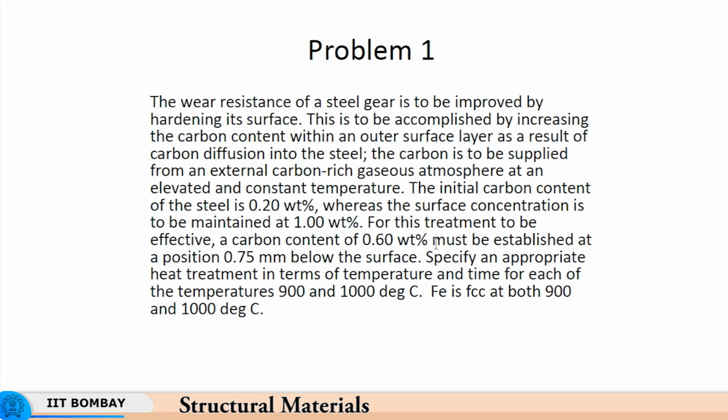So there is a gradient of carbon percentage from the surface to the interior. It is not a step change from 1% to 0.2% at an interface, otherwise that also would be disastrous. So there is a continuous gradient. A certain thickness will have 1% carbon, and as you go inwards, the carbon percentage will continue to reduce, and it will reduce to 0.2%. So there will be a small region of transition from 1% carbon to 0.2% carbon. You will not have just one single plane where there is a step change or an abrupt change from 1% to 0.2%.